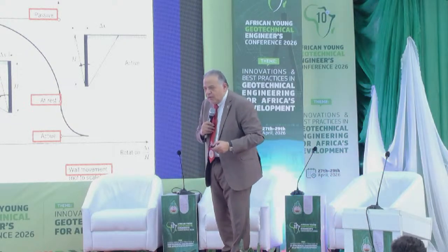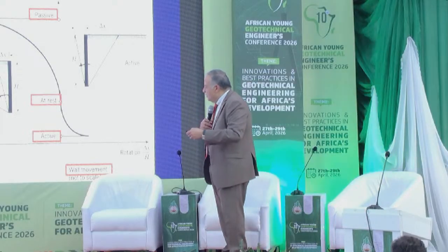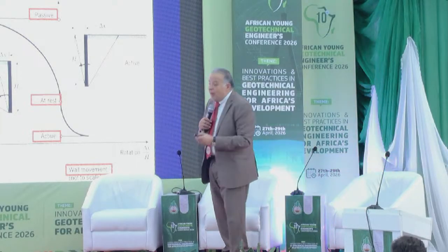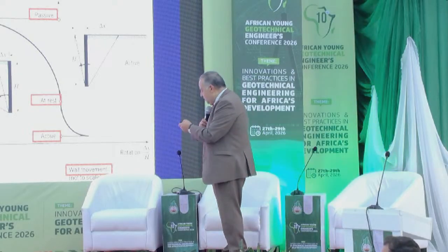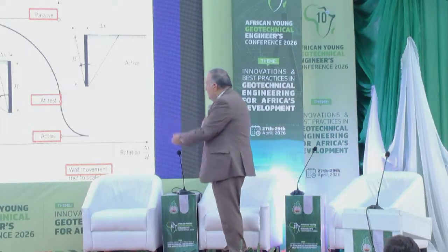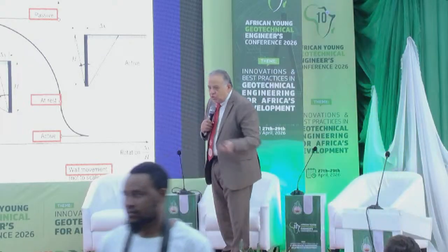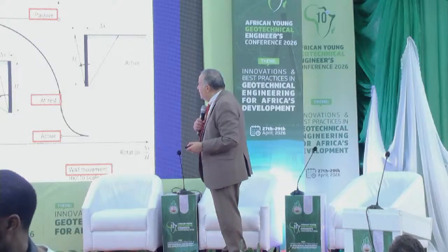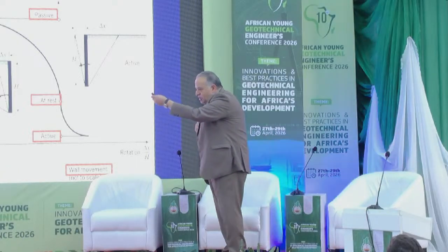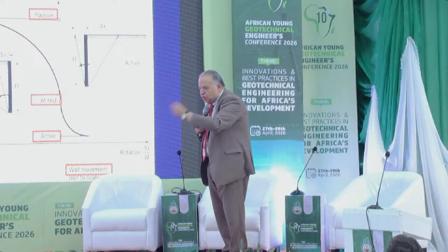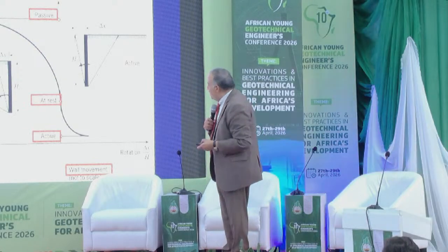If we have a wall retaining soil, then the direction and amount of movement determine the earth pressure. With no movement, we have at rest. If the soil is pushing the wall, then we have active earth pressure. On the other side, with large displacement, the wall pushing the soil, the soil gives a resistance, which we call passive resistance.